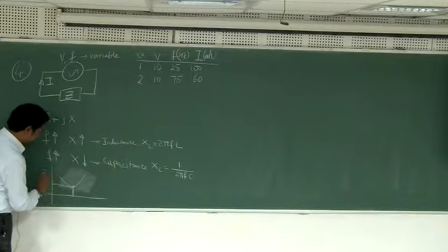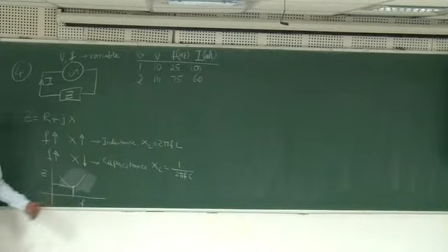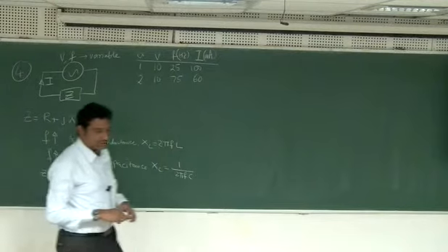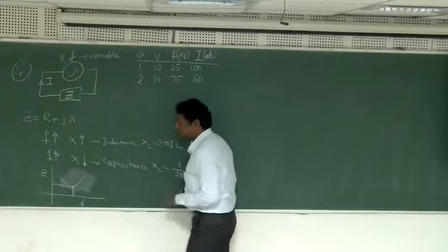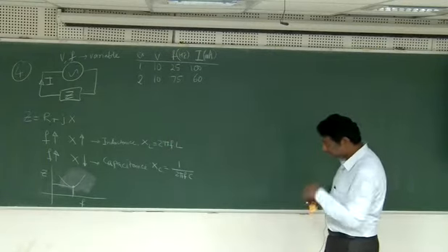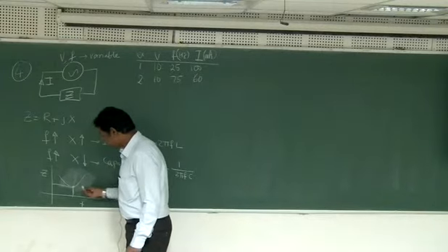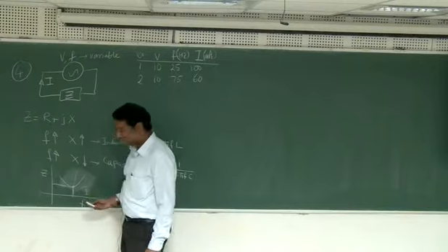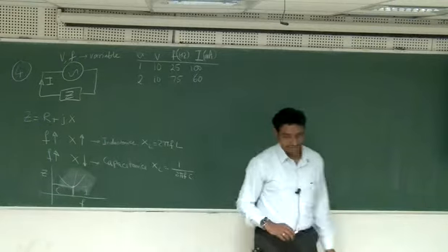where the impedance versus frequency, where the impedance is minimum at this point, what is the reactance? So the reactance will be 0. XL and XC both will cancel each other, and then it will be 0. Okay. So you can check that. On the right side, the circuit will be inductive. On the left side, the circuit will be capacitive. Is it so?